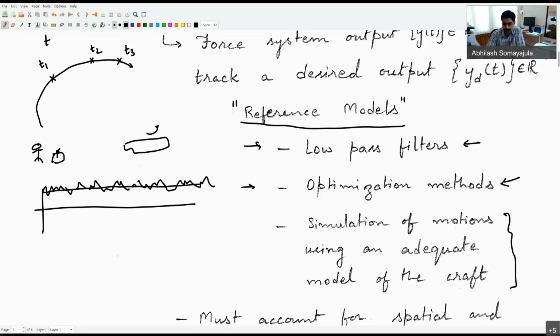So I want to go from point A to point B, but using the lowest fuel consumption, and I have certain constraints like I can't travel sideways on my boat and I can only travel at certain speeds. My rudder is effective at different speeds in a different manner. How do I take all those constraints into account? A typical way would be to form an optimization problem around it with an objective function, try to minimize it, and then try to find a possible path from point A to point B.